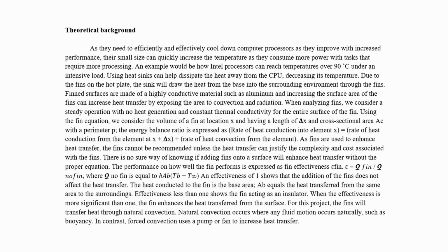The sink will draw heat from the base into the surrounding environment through the fins. Fin surfaces are made from a highly conductive material such as aluminum, and increasing the surface area of the fins can increase the heat transfer by exposing the area to convection and radiation.